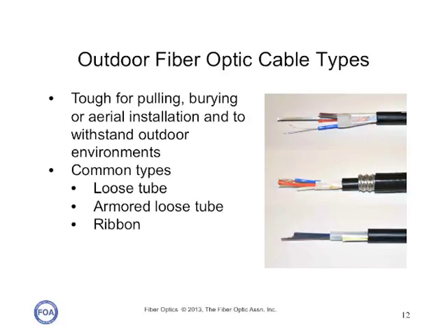That cable can be armored, as the cable in the center shows, to protect it from damage after it's buried directly in the ground, and that includes damage by chewing by rodents, because they love to chew on the jacket of the fiber. Ribbon cables lay all the fibers out in a ribbon and create a cable that has much, much higher density, that is to say, more fibers in a smaller cable.